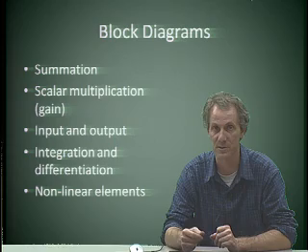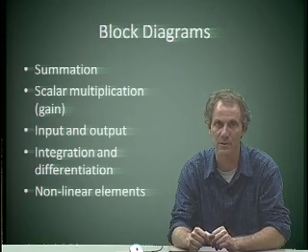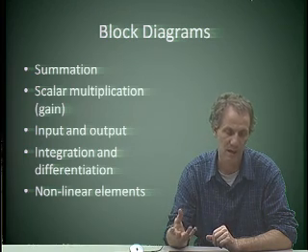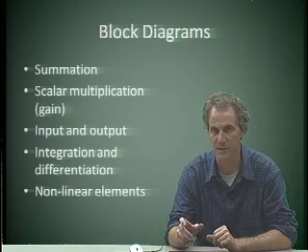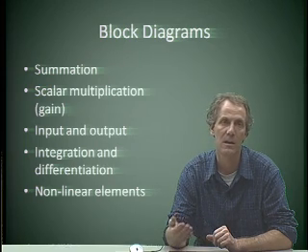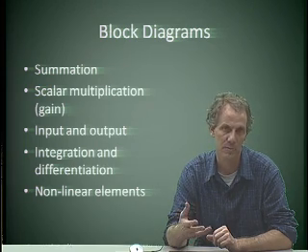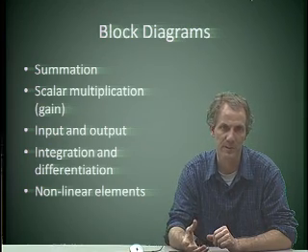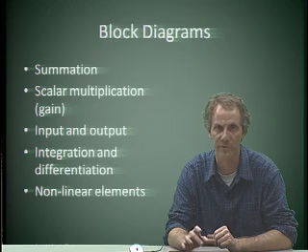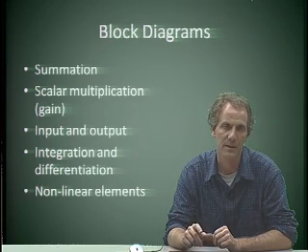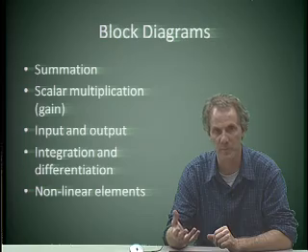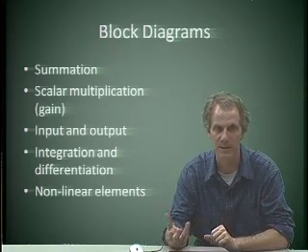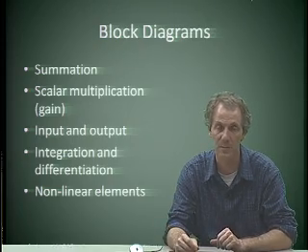That's necessary so you can actually use Simulink, which is all about drawing these diagrams and then just making it do the analysis. The blocks I'll show you: summation, which could also be subtraction, so subtraction or addition; scalar multiplication, which again could be times a fraction, so that could be your scalar division also. I won't do anything with matrices in Simulink, just scalars. Then you got input and output from the model, so you got constants or functions that come into the model. You have different ways of outputting stuff from the model, and I'll talk about that just a little bit.